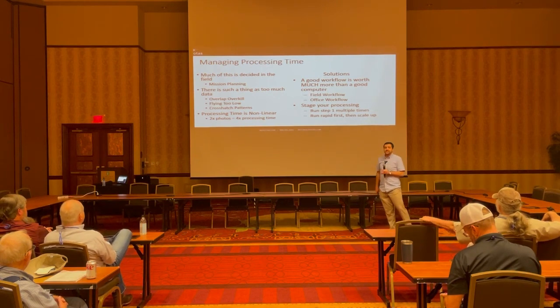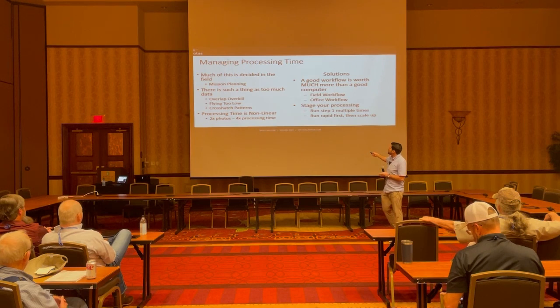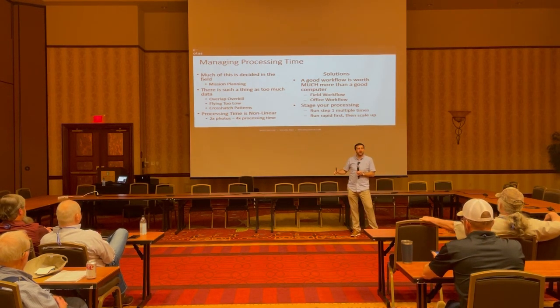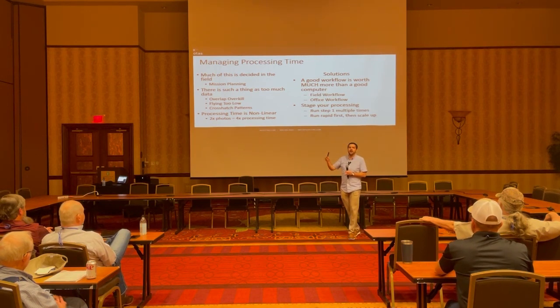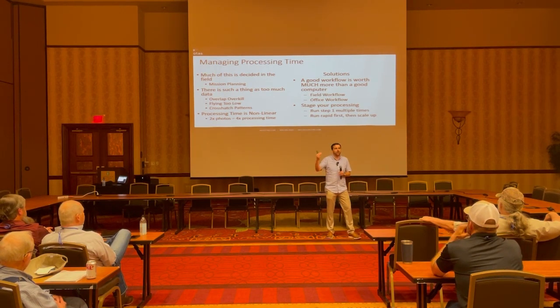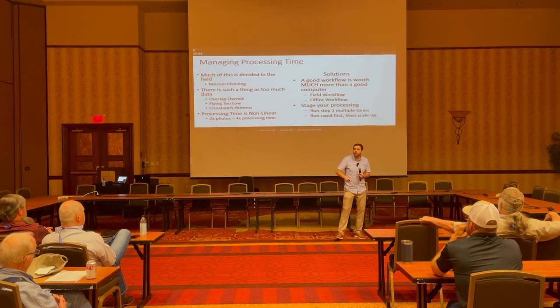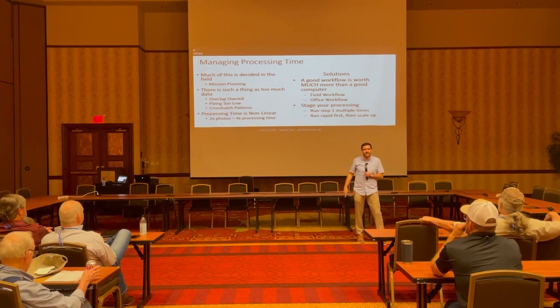For managing processing time in the photogrammetry step, honestly, a huge amount of this is decided in the field with mission planning. If you are struggling with processing and you're saying, photogrammetry is taking me days, there are all of these errors, it doesn't come out right, there's a better than even money chance that the solution is not in your software or computer or even office workflow, but it's actually in your mission planning for how you collected that data.